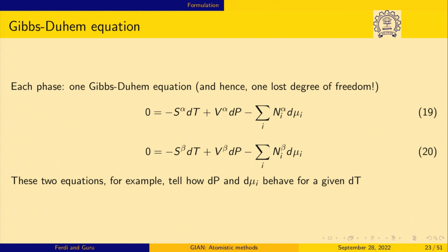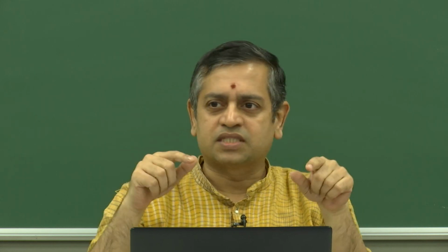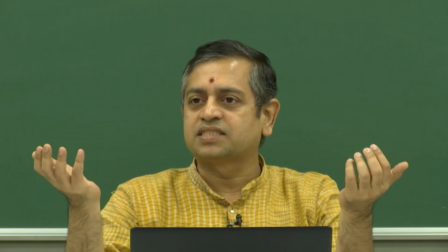Gibbs phase rule. This is why Griffiths' paper is also nice, and in fact, I came across that in the context of how all these lever rules and surface constructions fail when you have elastic stresses, because elastic stress depends on the configuration. If you take a precipitate as one single particle, you will get some elastic energy.